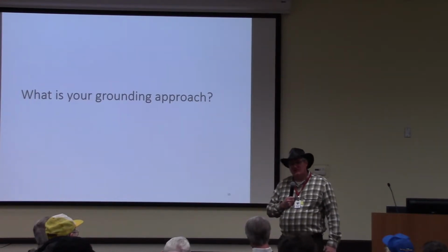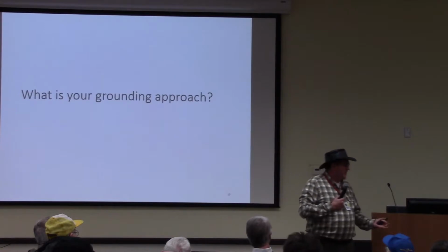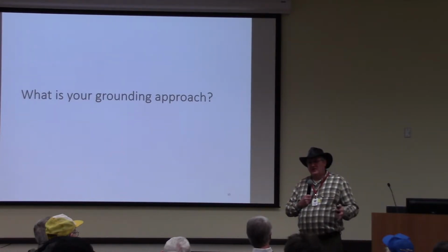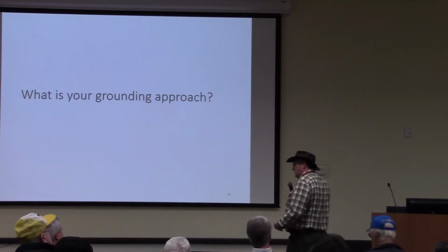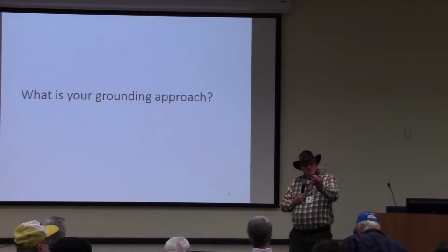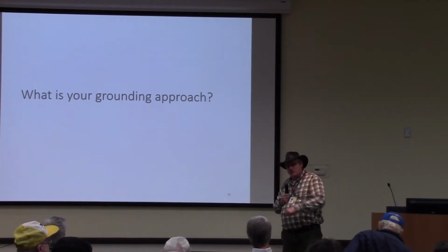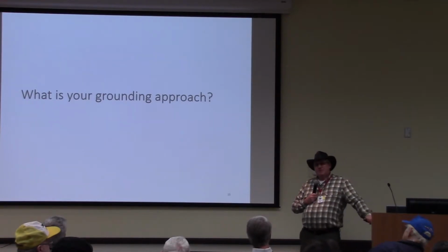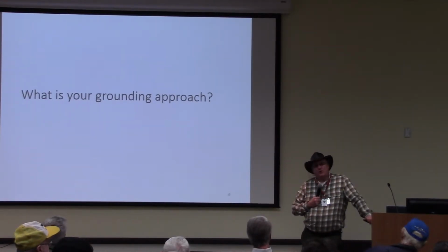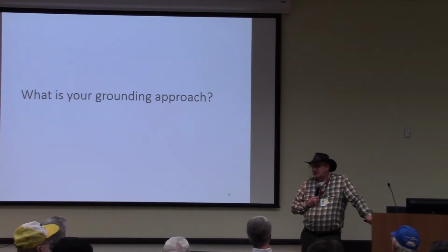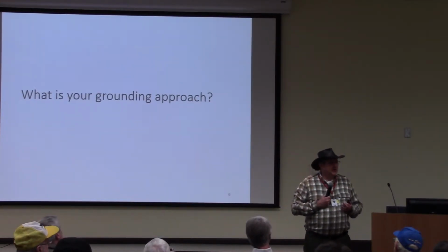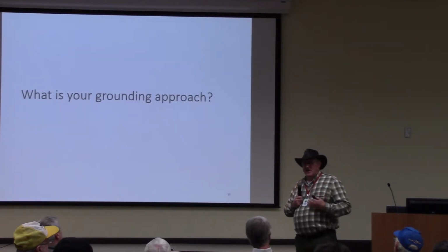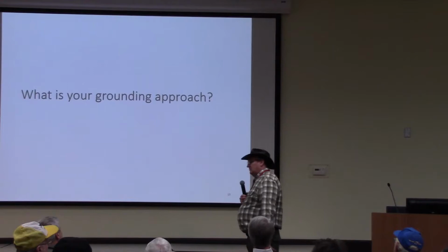Okay? An insulator is only as good as the surface it has. If you've got dirt and debris in those marbles, then they're going to have a little more conductivity than the glass marble itself. Now, it will help. It will lower it. It'll be better than just throwing it on the table. But it's still not a solid solution. Now, if you disconnected it and threw it out the window, and it was laying on the ground out there, that would be better. Because what we're going to talk about is how do you ask the lightning currents to stay outside of your house, outside of your communication shack.